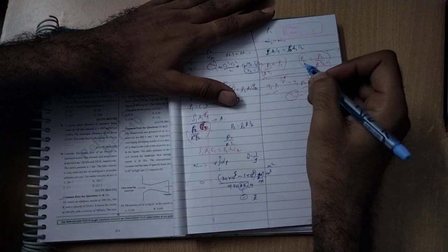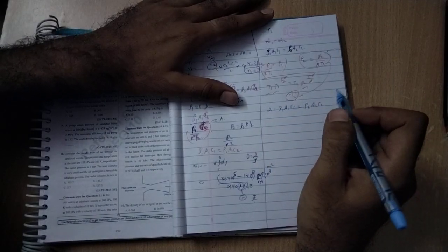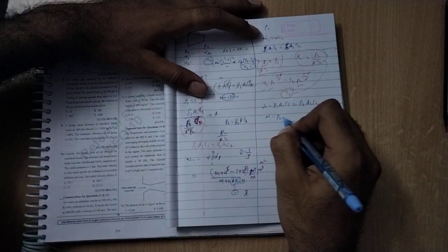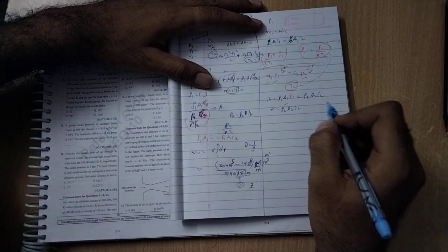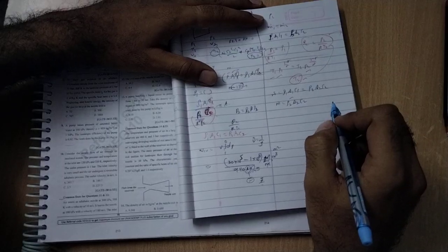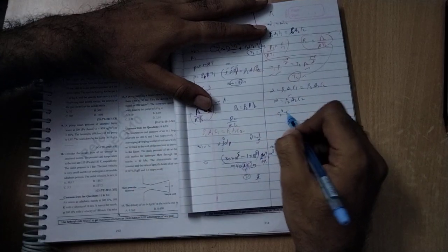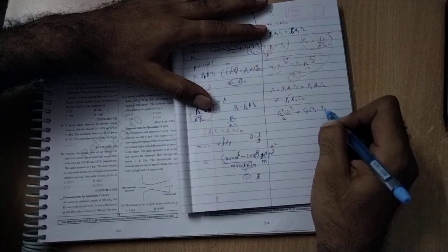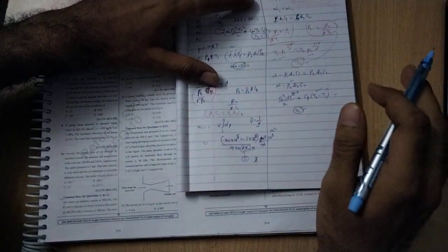So what will be the mass flow rate? Since m dot equals rho 1 A1 C1 equals rho 2 A2 C2, m dot equals rho 2 A2 C2, because the exit area is given and the exit density we also know. But what will be C2? You can see from the reservoir, (C2 square minus C1 square) divided by 2 plus Cp (T2 minus T1). Since we know T1 and T2, by this you can calculate C2. Put it here and you will get the answer. Simple question, I think you can understand.